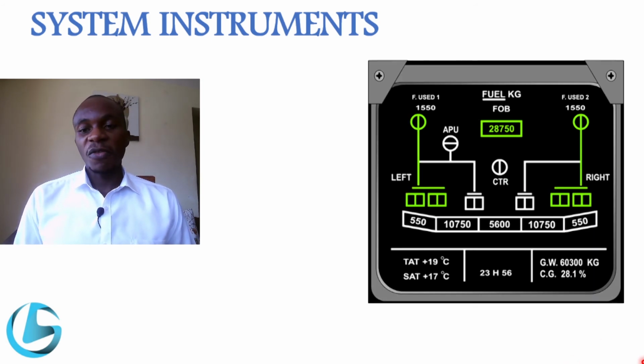Next picture we have is for the fuel system. This basically shows us the system of the various tanks on an aircraft. We have the left tank and the right tank and the center tank. It shows the amount of fuel in the respective tanks. And it also shows the valves from the tanks to the feeding system, maybe to the engine or to the APU. It shows if the valve is open or closed. If the crossfeed valve also is opened or closed, on some aircraft there's an indication provided for the crossfeed valve.